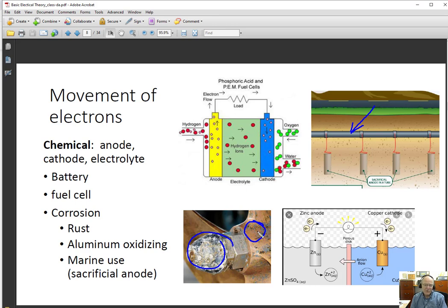It's very hard to move a boat if your propeller disintegrates and goes away. So this piece of zinc is attached to the bronze, and it's often used as well with aluminum. That piece of zinc is attached because zinc is less noble, and electrons flow in a current through an electrolyte from the zinc into the bronze.